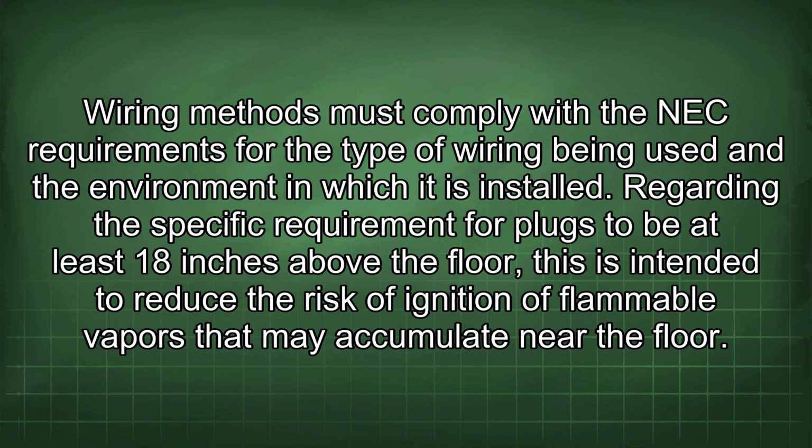Regarding the specific requirement for plugs to be at least 18 inches above the floor, this is intended to reduce the risk of ignition of flammable vapors that may accumulate near the floor.